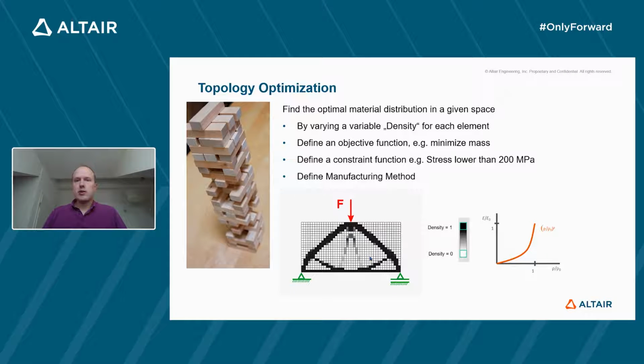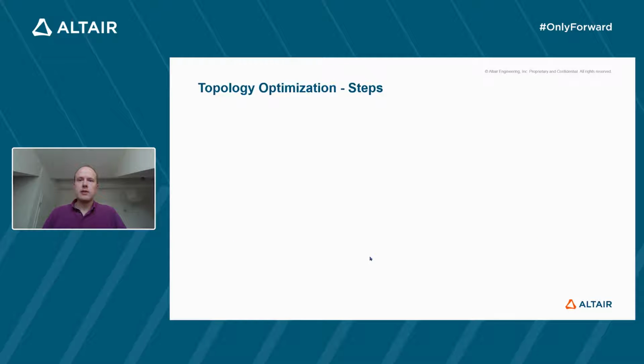All right, now this is implemented in Inspire Structures, and what you need, of course, as a basis for the optimization is a finite element model with forces and boundary conditions. And now these boundary conditions can be, for example, determined from either a pre-existing part or from an engineering code. But of course, you can also determine these loads and forces that occur from a simulation, from a so-called multi-body